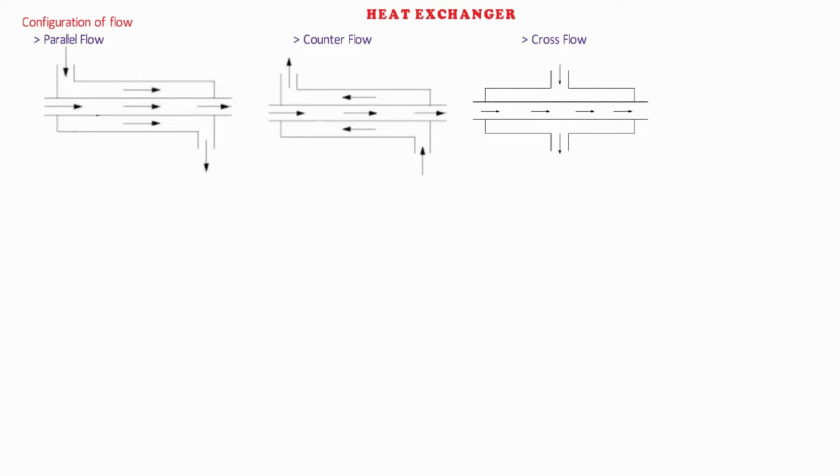To increase the efficiency of heat exchangers, they are designed to maximize the surface area of the wall between the two fluids while minimizing resistance to fluid flow through the exchanger. The exchanger's performance can also be affected by the addition of fins or corrugations in one or both directions, which increase surface area and may channel fluid flow or induce turbulence.